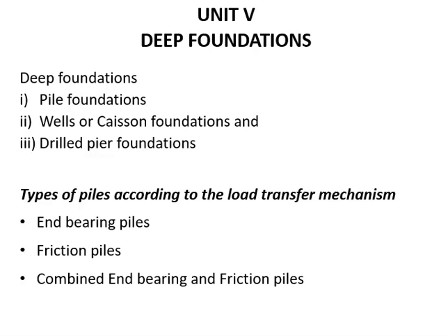Types of piles. There are various classification systems available: based on the composition, based on the method of installation, based on the load transfer mechanism, based on the use, based on the displacement of soil, based on the shape of the pile, and also based on the size. Based on the load transfer mechanism, the piles are classified into three types: end-bearing piles, friction piles, and combined end-bearing and friction piles.